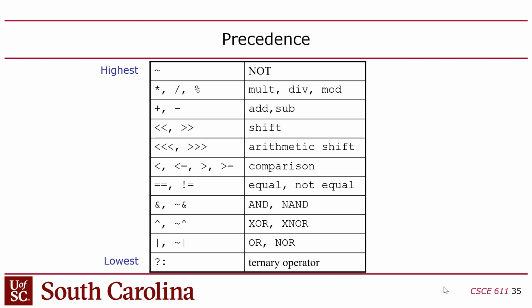But if you compare, like inside of an if, X double-equal X, that will be false. You might think, no, X is equal to X. Well, no, but X doesn't really exist in real life. It's just a concept. So double equal is for hardware, synthesizable code you want to put in hardware, and then you can use the triple equal when you write a test bench, because then it allows you to compare to non-existent values like X and Z. Okay?